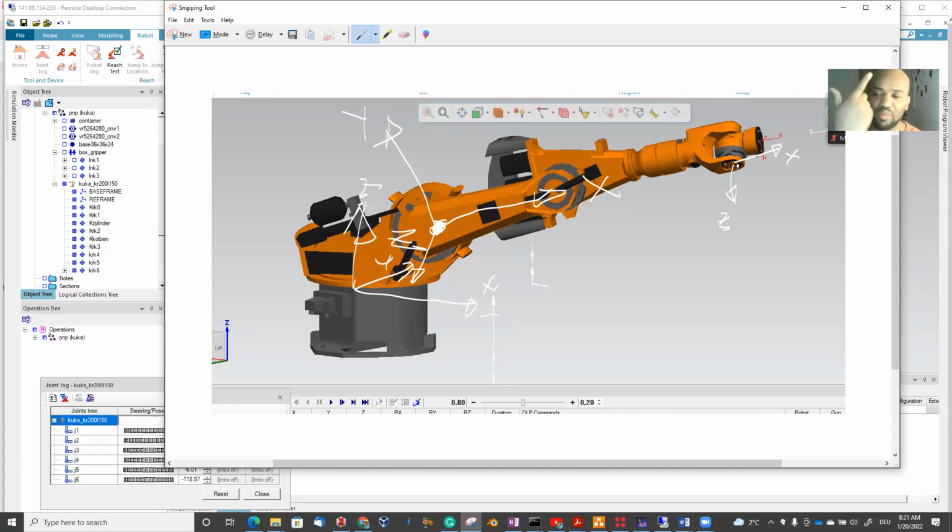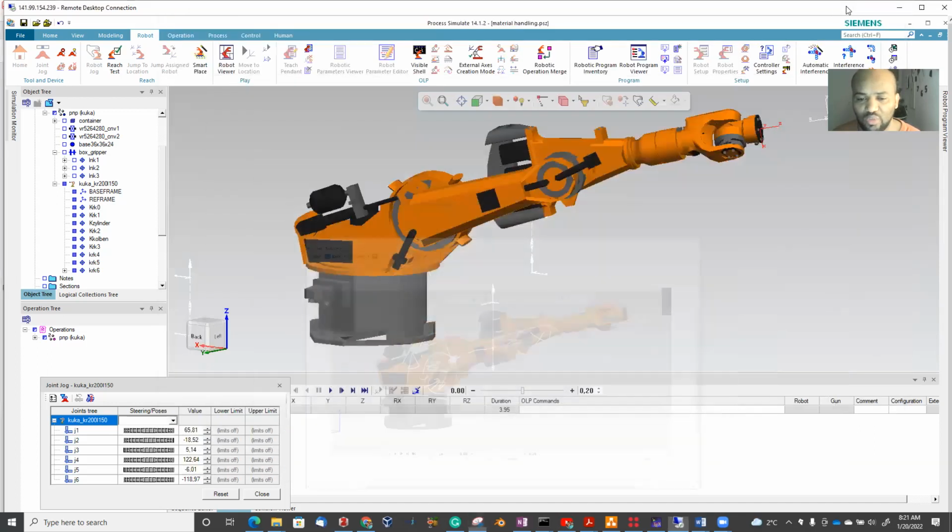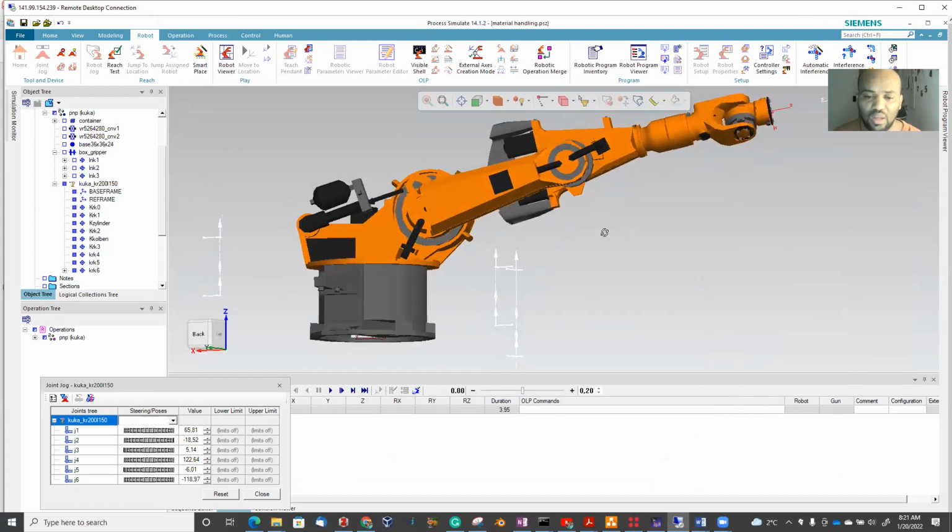Just use your fingers, point your fingers, and then you will have something like this. And so on, this way you can assign the axes. So always note x should be assigned here, y should be assigned here, z should be assigned here, according to the axis of rotation, the axis of links, and the right-hand rule. So this is a convention, so we have to follow it. Otherwise it's wrong. Otherwise it doesn't work.